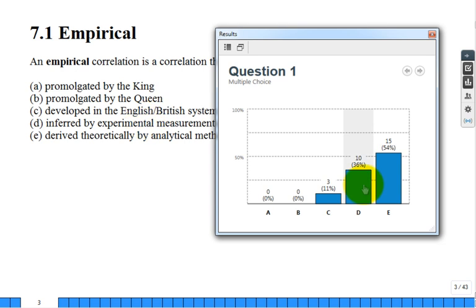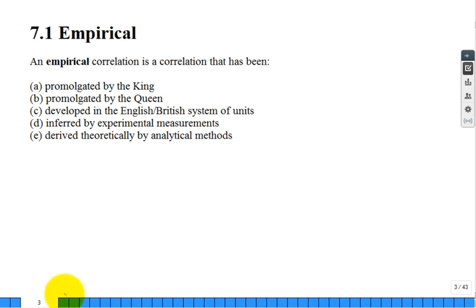Anyway, it's based on experimental measurements. That's the key. It's not derived analytically or theoretically. It's just based on a lot of measurements, and then they do some curve fitting of those measurements. They often take the physical measurements and put them into dimensionless groups or parameters, such that you'll have some abstract Nusselt number as a function of the Reynolds number, and they'll have a sequence of data points, and then they fit a line to it, maybe on a log-log plot to get the exponent.